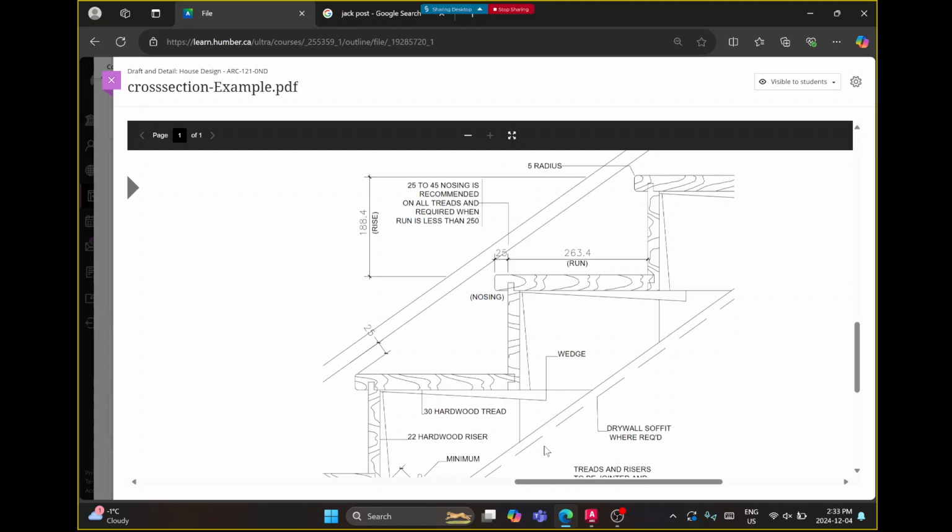And the reason for that, there's two reasons. One is that now you both have an understanding of how it works in detail, but there's also this liability difference. Let's say they do a shop drawing for this door, and I approve it, but they made a mistake, and they made this door handle on this side. I already approved the drawing, I gave them a check mark, I said yes, it's good, proceed with fabrication, and they install it. Now that it's installed, it's my fault if it's wrong. So now it's my money as an architect, I have to spend my own money for flipping all of these doors around or rebuilding them. It basically becomes my problem.